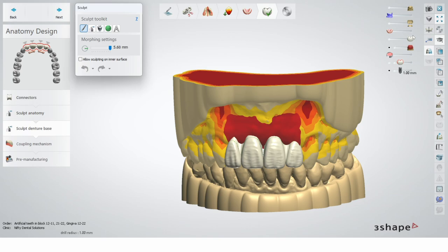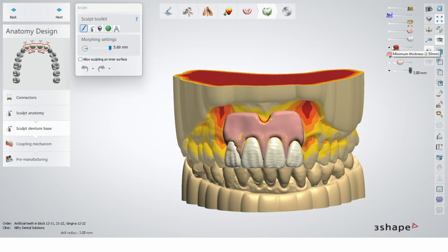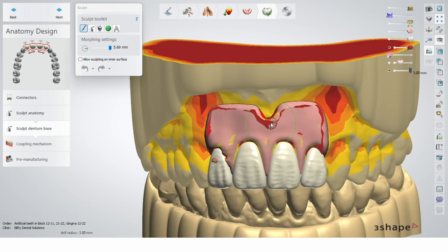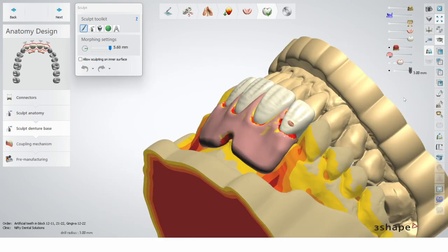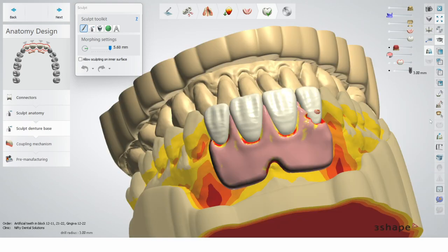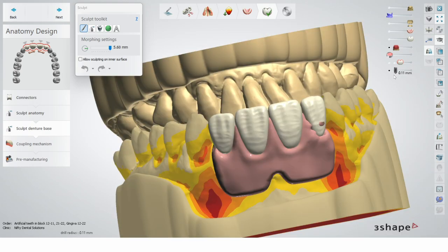So here you got minimum thickness, where I usually turn it on off, which is set to 50. So it means this area that are just tiny below 250, probably 248, but still mark it. And then this is for non-millable areas, but thank God we're not gonna mill these dentures. We're going to print them, so we don't care about parts that are not millable. So I'm gonna turn it off completely.